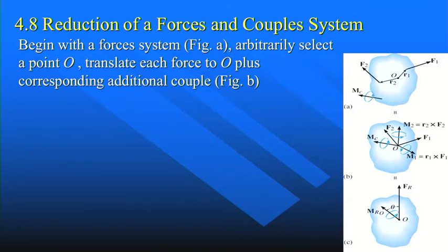Begin with a force system as shown in figure A. Arbitrarily select a point O. Translate each force to O plus the corresponding additional couple, shown in figure B. Then we get an equivalent force system.